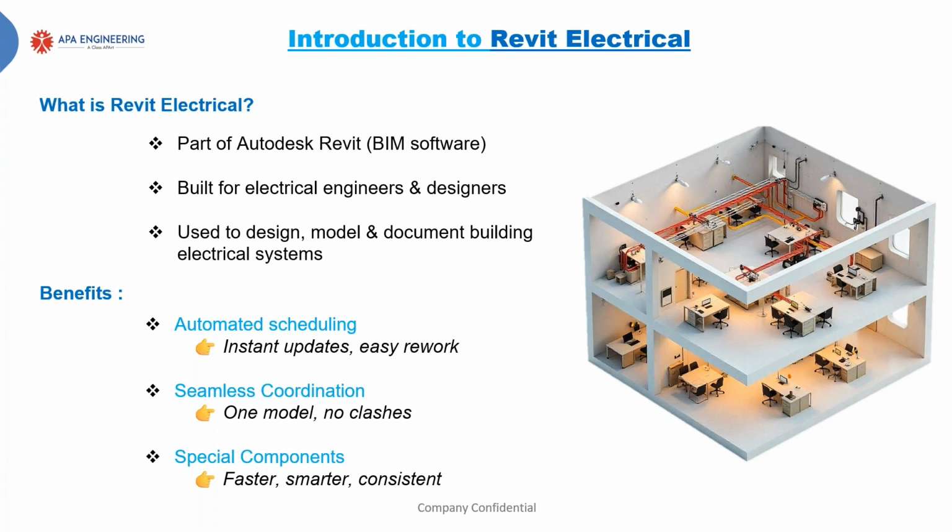In Revit, all the information related to the component is stored in the 3D model, and with a few clicks we can auto-generate the Excel sheet, which is called the schedule. How this helps is that any update we do in the model will be automatically updated in the schedule as well. So we don't have to do any kind of manual work for the schedule preparation.